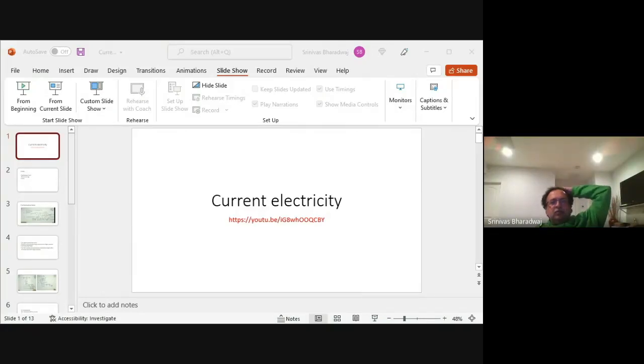Okay, so you can also go the other way. See, in this case, he has put I in this way, right? Look at the direction of his I. So he's going this way, right? From A, he starts at point A: minus 2 minus I times R1 minus I times RL minus R2 times I plus 4 equals 0. Okay, that's how you calculate.